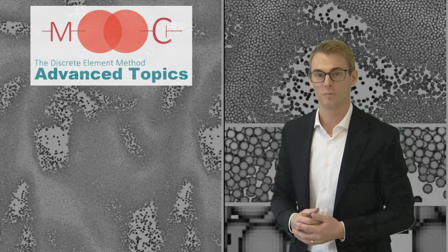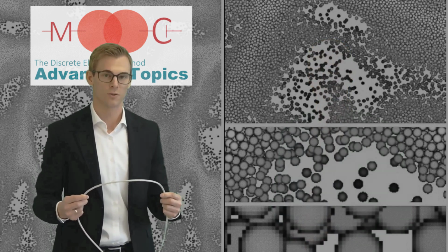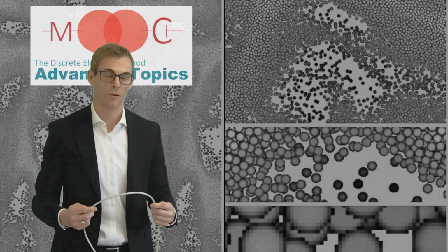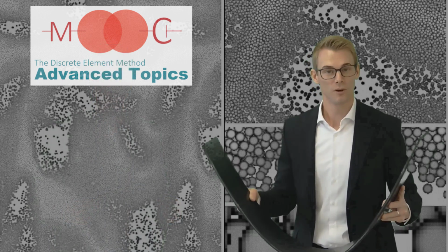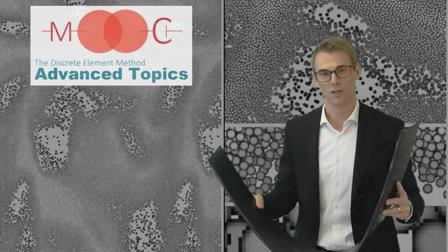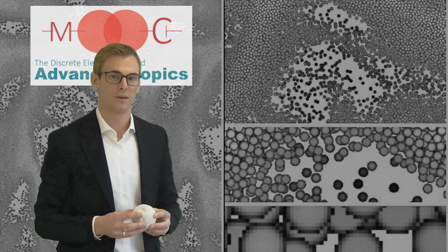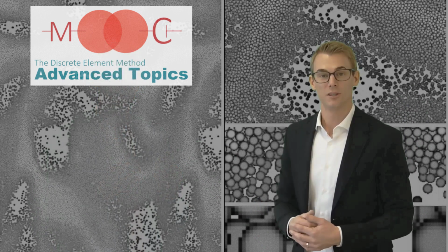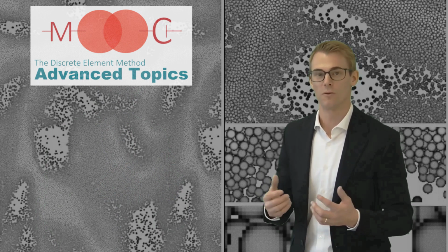Another categorization could be the dimension of the bonded particle model, where a 1D model refers to a single line of bonded particles, such as for the modeling of wires, ropes, or structures made of those, such as fences or rock protection nets. 2D models mean a layer of bonded particles, such as for the modeling of membranes or, as just discussed, for the modeling of conveyor belts. And a 3D bonded particle model would refer to the already mentioned rocks. Additionally, a mix would also be possible, for example, when a big bag is attached with 4 ropes on its edges.